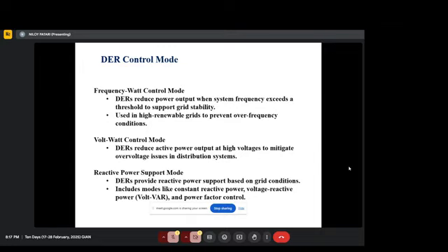Generally, it's a transient stability kind of operation. So we can improve the dynamic stability of the system. Whatever we have been doing right now in OpenDSS is steady state power flow analysis, right? Steady state meaning that loads are fixed, everything is fixed, there are no transients happening, just solve power flow. But in real time, you have a lot of dynamics going on in the system. Active power, reactive power, loads are always changing. If you don't stabilize the grid under such dynamics, then it's very hard to operate it, right?